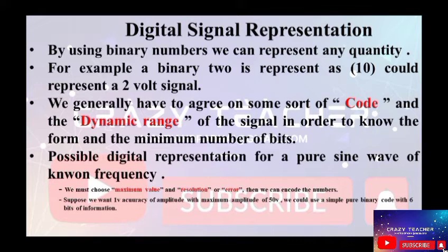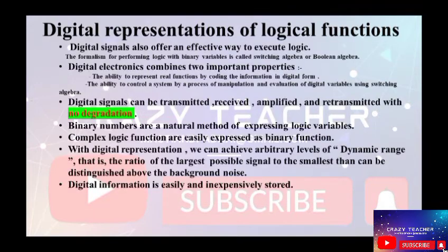So if we are looking for these exact values, then we have to go for the analog signals definitely. But as soon as we go for this digitization process, some amount of error is introduced into the system. We'll see that there are different types of errors that can crop up into these analog systems, and that makes the digital systems much better from that point. But as far as the initial quantization is concerned, digital signals have got some amount of error associated with it.